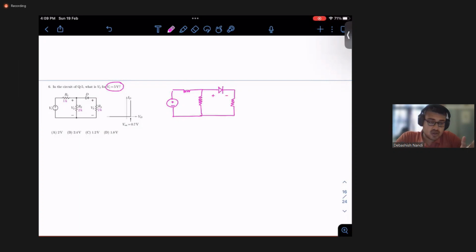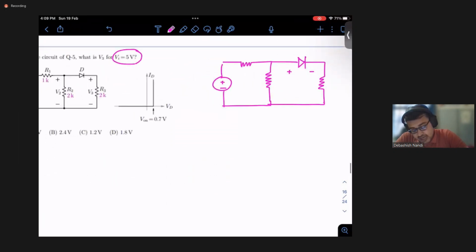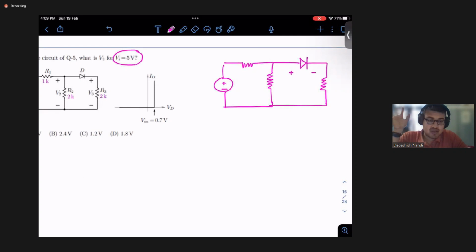And when the diode is on, from this concept, irrespective of what voltage you apply, the potential across your diode will always remain 0.7, irrespective of whatever the current is flowing through it. See, from this plot, if I take these 3 points, current is changing, right? But my VD remains the same, because this line is parallel to the y-axis.